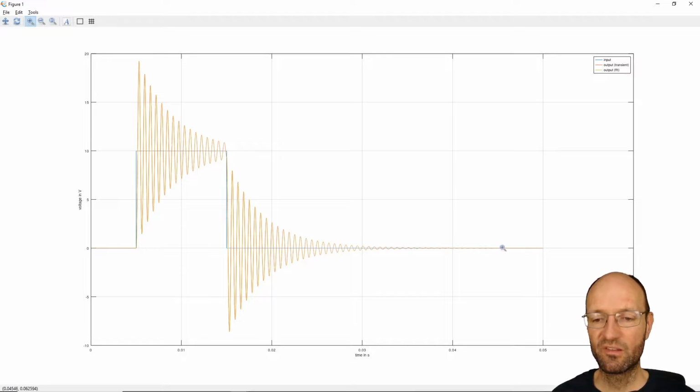Because it's still ringing here at the end, we also see this ringing here at the beginning, because it's replicating, and we start once again, and then it's ringing down, and we start over again, and so on. So for the FFT solution, we would probably need to wait longer or damp it more, so that we don't start with an oscillation already at the beginning. This is some problem, some artifact, as said, of the FFT.